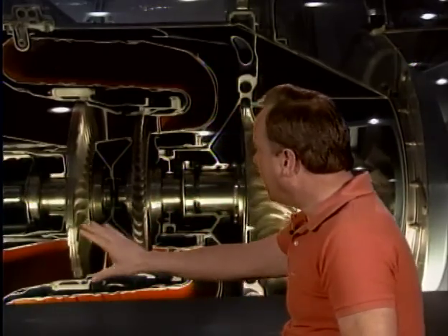They're going to ask you, how do you measure turbojet engine temperatures? Well, they are very high temperatures. The answer is you normally use a thermocouple, because thermocouples, as you remember, don't require an extra source of power, they generate their own electrical power. But what kind of thermocouple? Because it takes a special kind of thermocouple to stand that very high heat, and the answer is a Chromel-Alumel thermocouple, and you need to remember that for the test. Turbine engines normally use a Chromel/Alumel thermocouple because that stands the high temperatures involved.